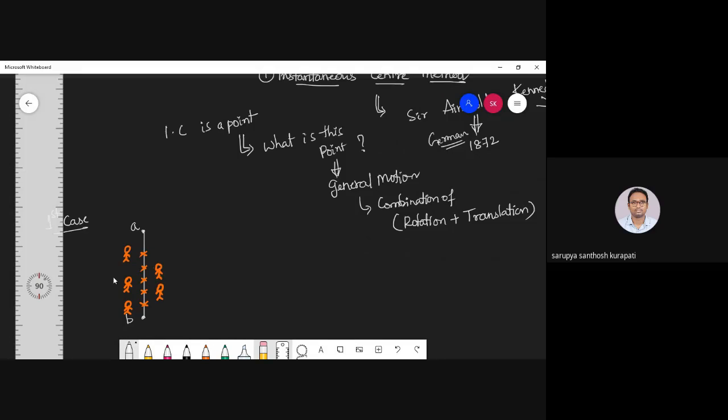or else simply I can say, suppose here this is my velocity vector. This velocity vector at present is perpendicular, that means at 90 degrees, to this particular line. So when the velocity vector is perpendicular, please do remember this point. Wherever you sit on a line which is perpendicular to the velocity vector, here your stick AB is exactly perpendicular to the velocity vector, so you will observe a pure rotation at this particular point.